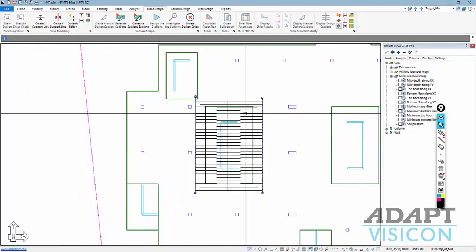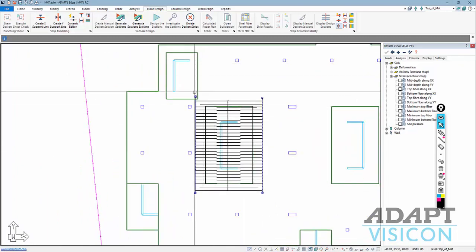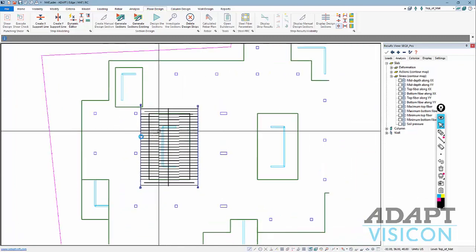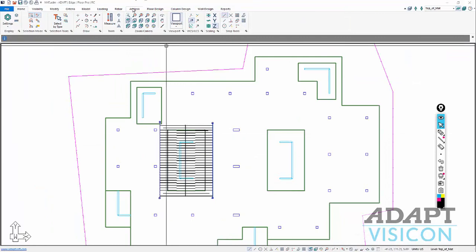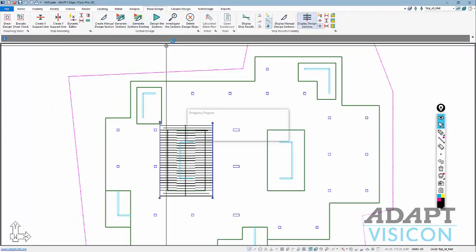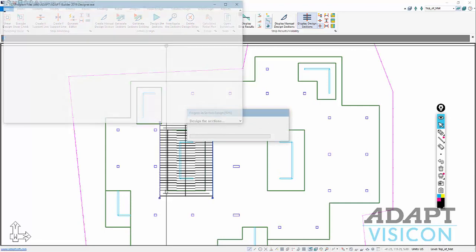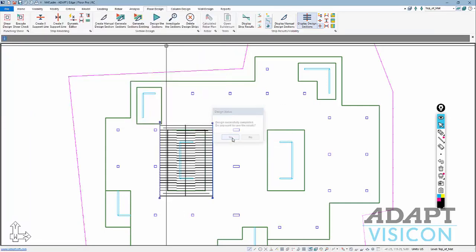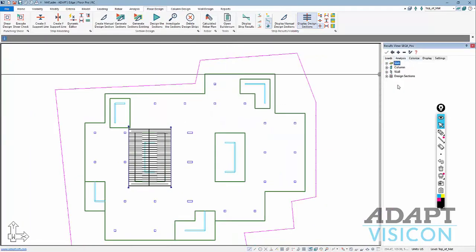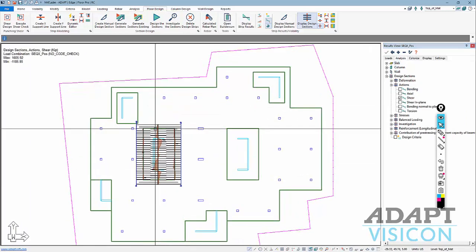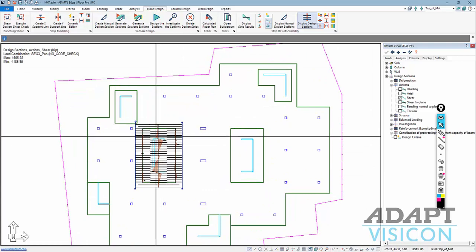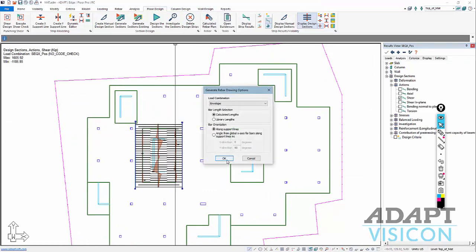Floor Pro mode because this is technically an elevated slab in the program. So we would have to be in Floor Pro mode to design the. Okay, back in Floor Pro mode, I'll go back to Floor Design, design the sections, and within those strips, we can now obtain just different actions along the cut path. So we'll go to actions, for example, bending, shears, etc. And based on these cuts, the program will add reinforcement for the different combinations that we've evaluated.